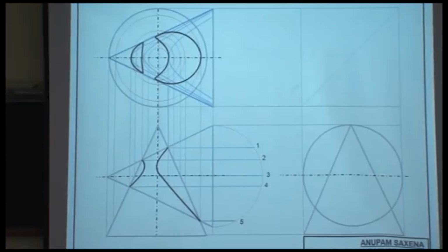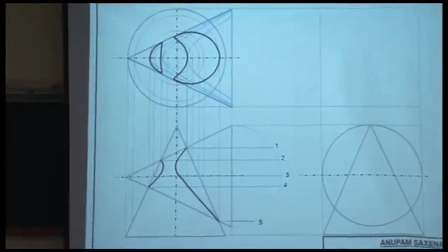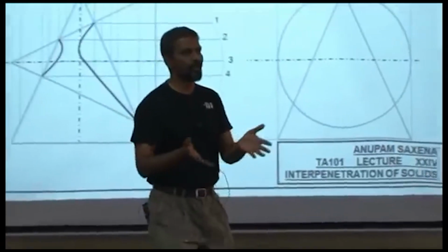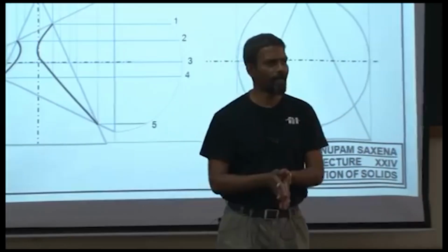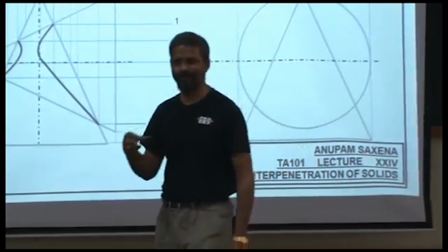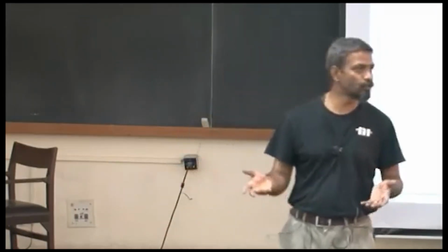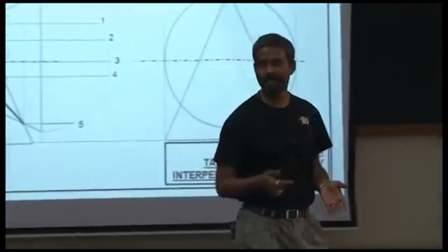Now, Avikalp. So I was interacting with him yesterday, right? And he was like, you showed that cone hexagonal prism assembly yesterday or Tuesday, and how did you cut the cone for your hexagonal prism to be fit precisely into it? And to which I said, well, if you want to learn how to cut it, first you have to figure out the intersection contour between the two solids and use the information that one of the solids is developable.